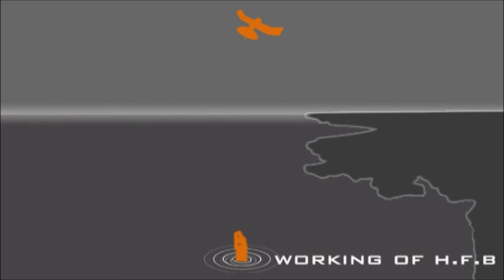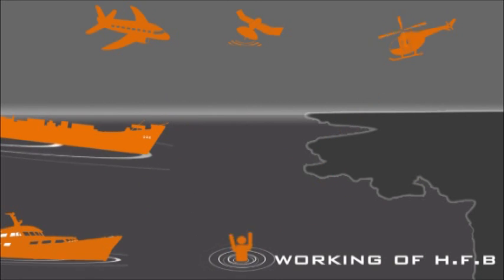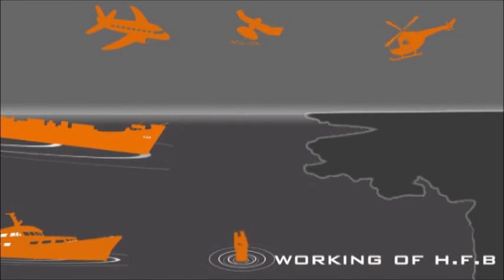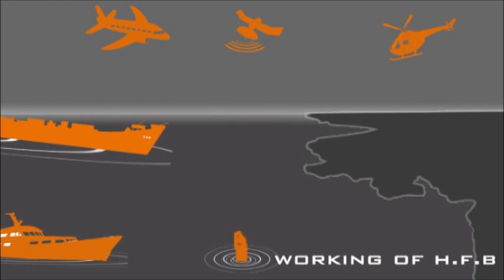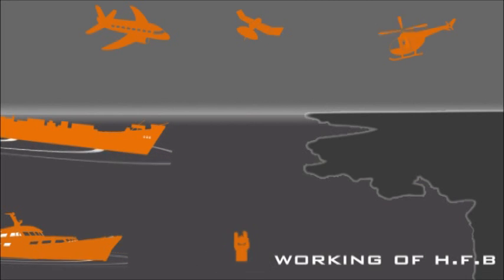The beacon transmits the distress alert to a satellite. The satellite locates the beacon position and transmits this information to a land station, which in turn transmits the information to the Rescue Coordination Center. Beacon's operating frequency is 433 MHz. It has a hydrostatic release unit which is released when the vessel sinks. The beacon device emerges on the surface of water and starts to transmit distress alert. This is the exact working of the beacon device when it is put under distress.